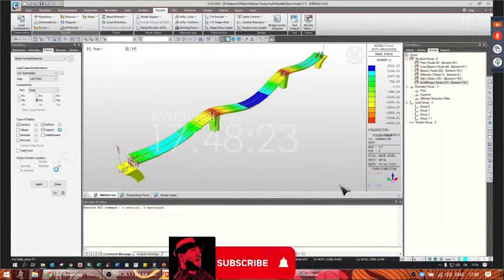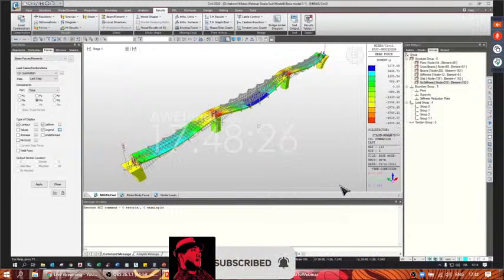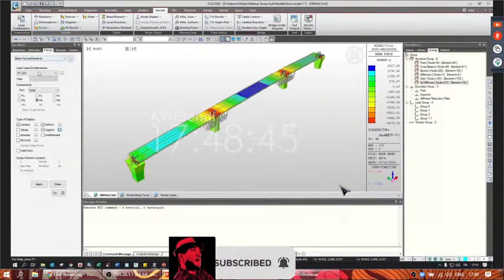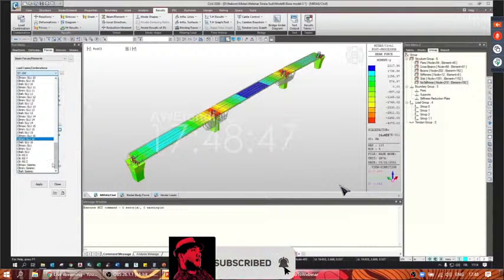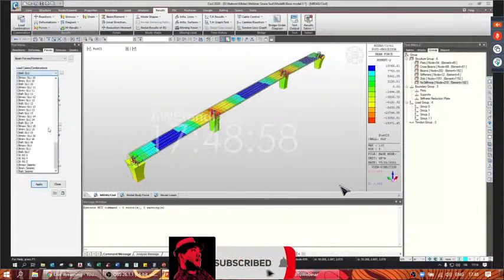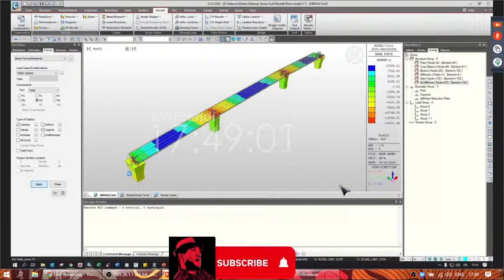Then we have stage 1 with the addition of the slab. And finally, we have stage 2, that is the final stage, with also the pavement added. So we can see in the post-construction stages the load combinations we defined. For example, we can see the envelope of the ultimate limit state combination. Okay. And also the seismic envelope.